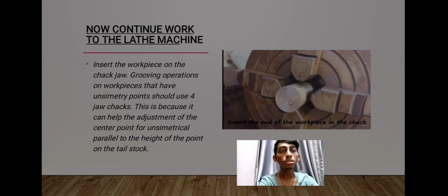Insert the workpiece on the jaw. Grooving operations on workpieces that have unsymmetry points should use four jaw chuck.